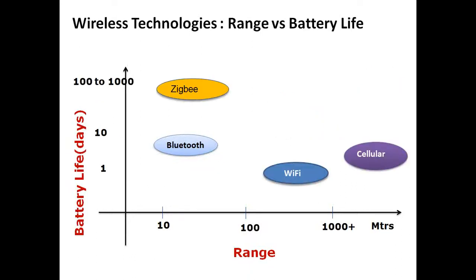And the fourth one, which some of you may not be familiar with, is the Zigbee. This is the low power RF technology for short range communication or very small network communication. You can compare Zigbee to Bluetooth or RFID that you may be aware of in terms of the performance and the usage. Zigbee has a range, depending on how you measure it, anywhere from a few meters to hundreds of meters. And it has a theoretical bandwidth of 250 kilobits per second, but achievable bandwidth may be a little less than that.